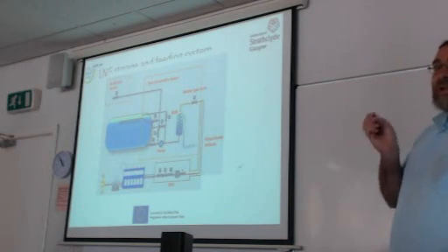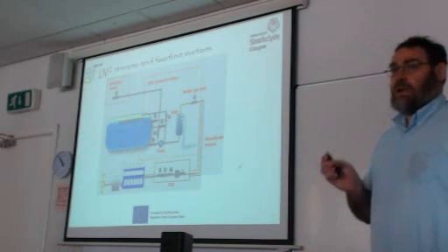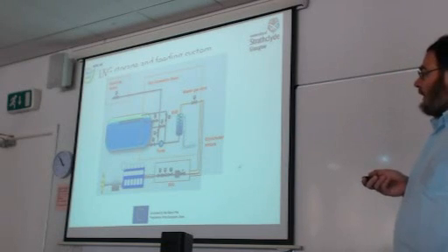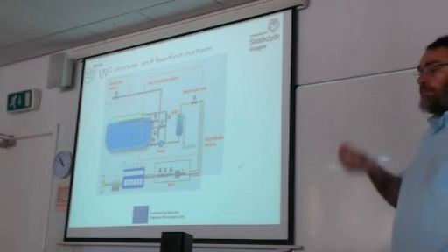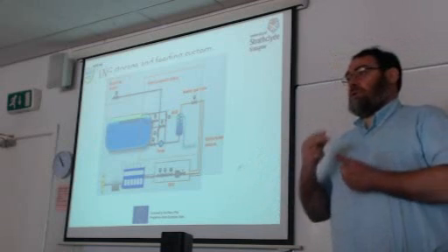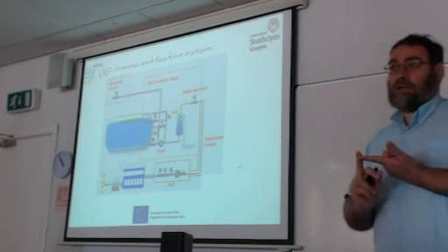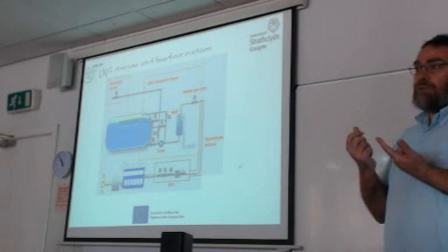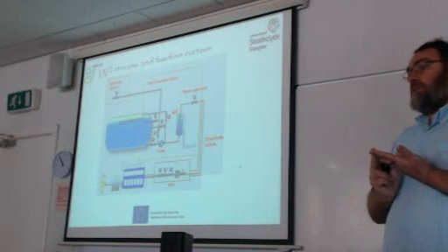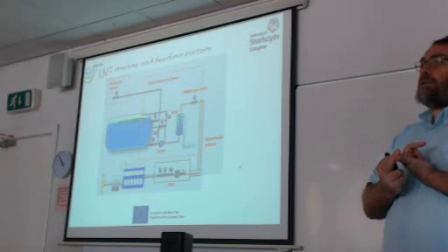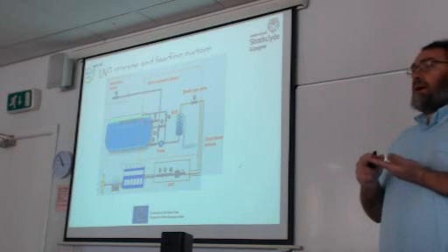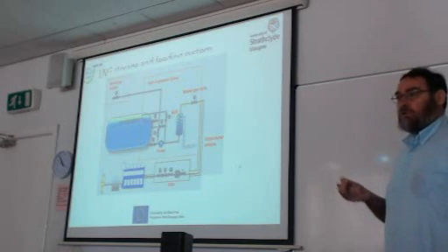So in this case, this is a concept for a four-stroke engine, and this slide shows the storage and feeding system. Certainly in the engine, natural gas in gaseous form will be injected, usually at ambient temperature. But then there is another problem. In which form will the fuel be stored? Will it be stored in liquid form? Will it be stored in gaseous form?